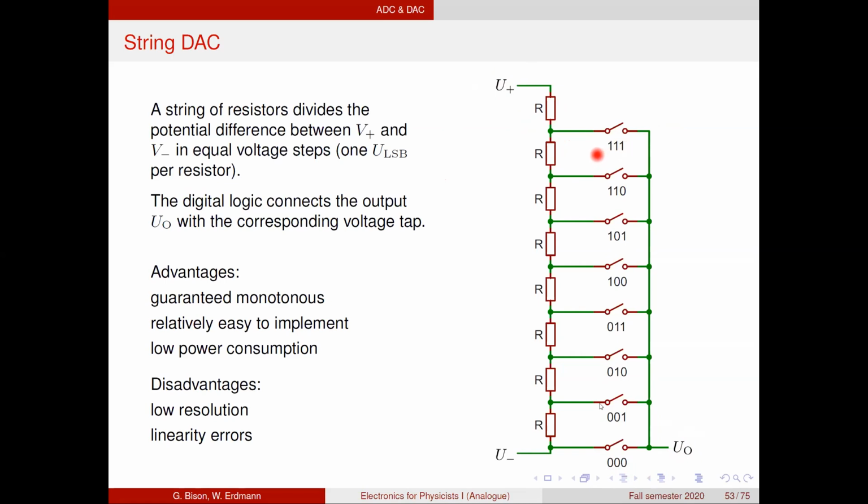And typically this is omitted because we don't want to build a digital system which just carries 1 more bit in order to just get this 1 more level. If it's only 8 levels, this looks significant, but of course, if you have a 20-bit DAC, then it's only 1 part in a million that you lose here. But this is a typical way to scale the output between the digital values and the analog voltages.